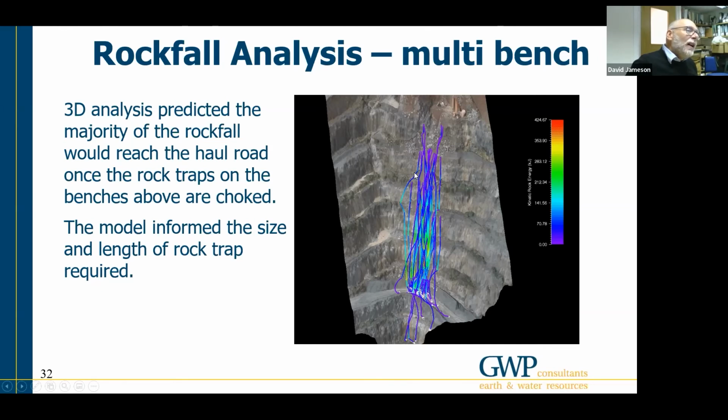Incidentally, you can see to the left-hand side here, very similar to the last video that I showed, that one of the blocks that has come off and is modeled here goes off down the side of the debris pile, and then bounces away from the initial line which you would assume would be your most critical line, and has a different rock path to the bottom. So there's a need evidently here for 3D rockfall analyses, because that accommodates changes in topography outside your initial rockfall line.